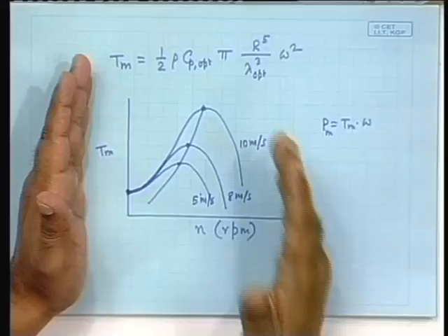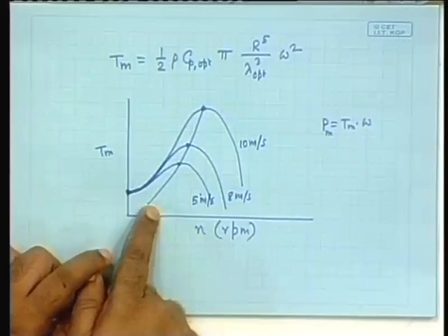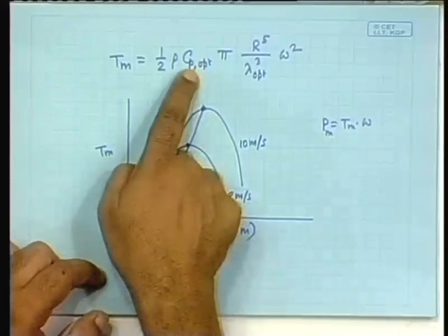So, that is the back torque that comes whenever you generate and actually use the electrical energy. Here also the same thing will happen. So, this is the character of the generated torque, and there will be a corresponding character of the load torque. Now, if this wind turbine is supplying, for example, a water pump, then the water pumping has its own characteristic feature of the speed versus the torque, okay, and these two will have to be matched. Why? Because you want to operate on this line all the time. This is related to the optimal value of the Cp.